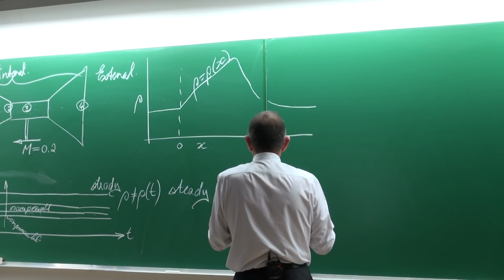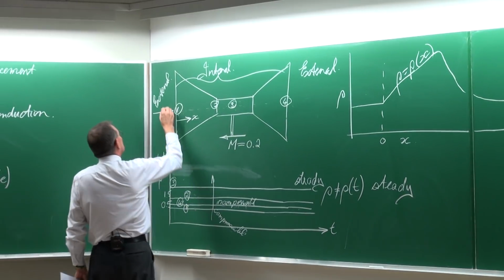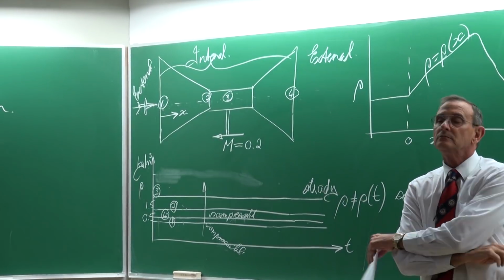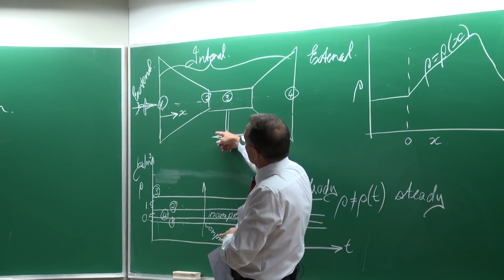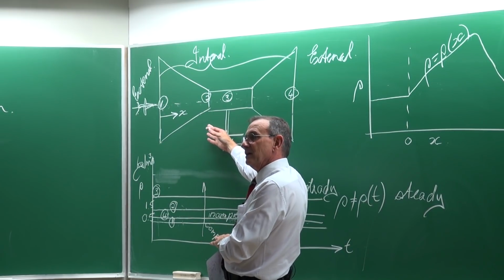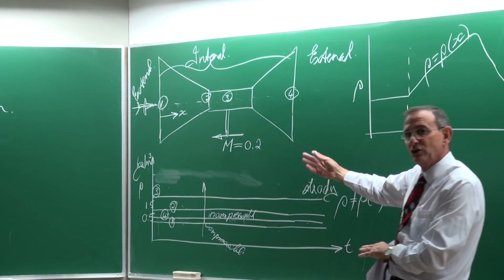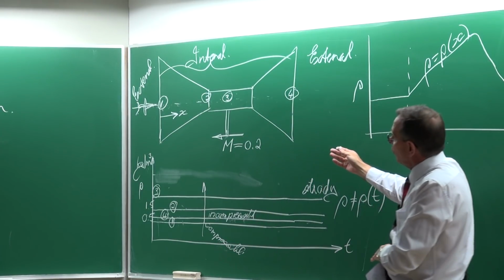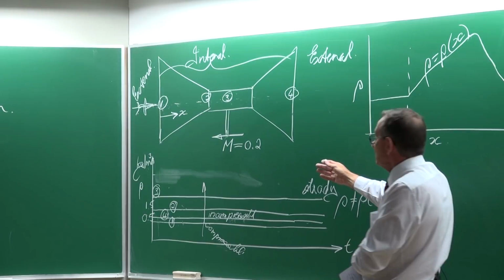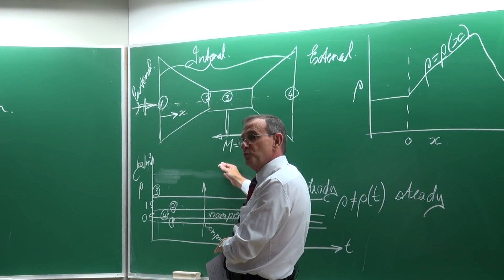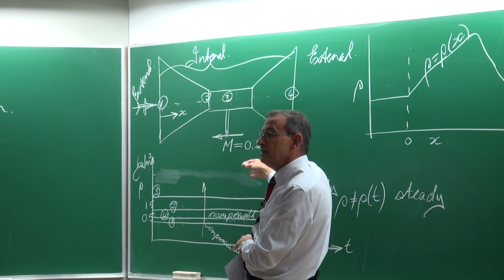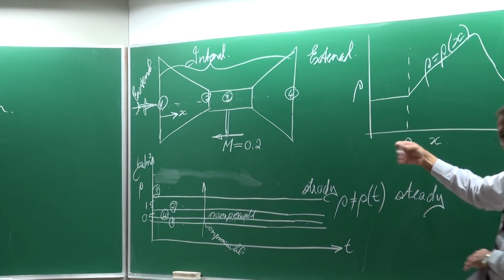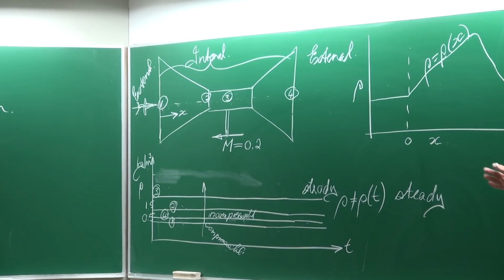Now let's suppose the case of the bird strike. So here comes the bird, and it goes right through the turbine. In case you don't know, bird strike is of course a very risky thing for any aeroplane during takeoff. Because of that, there were quite a few accidents already. And what they do typically, if they design a gas turbine engine for an aeroplane, is they do experiments. And in the experiments, they do not use live birds, but they use frozen chickens. And it should be able to go right through the turbine or right through the aeroplane.